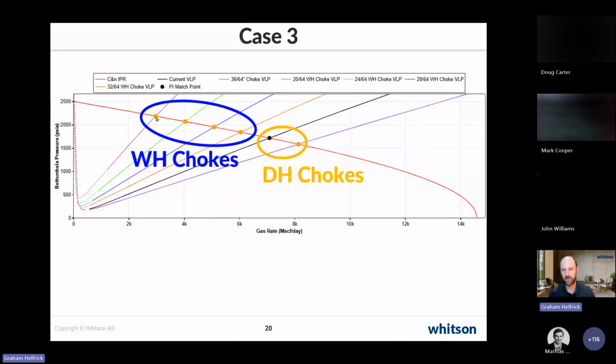One thing I'll mention is, people say if I have a surface choke, when I want to calculate my bottom hole pressures, what pressure source should I use? Should I use the line pressure, which is on the downstream side of the surface choke? Should I calculate through the surface choke and then calculate down the wellbore? And the answer is no. Typically we want to use the most simple calculation possible to get bottom hole pressures. And so in the case of our surface choke, there's 2 options. We have a line pressure as our pressure source, which is typically on the choke outlet, or we have a tubing head pressure, which is on the upstream or the bottom of the wellhead choke.